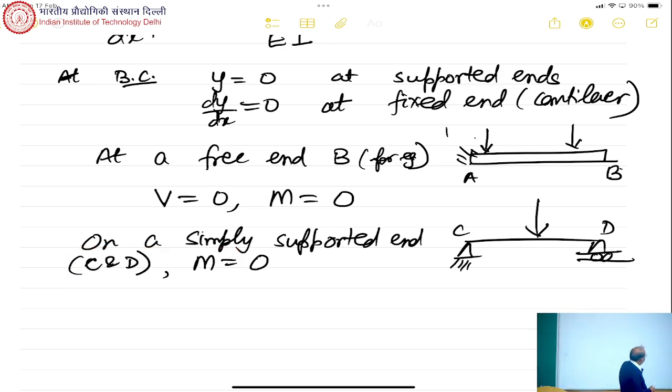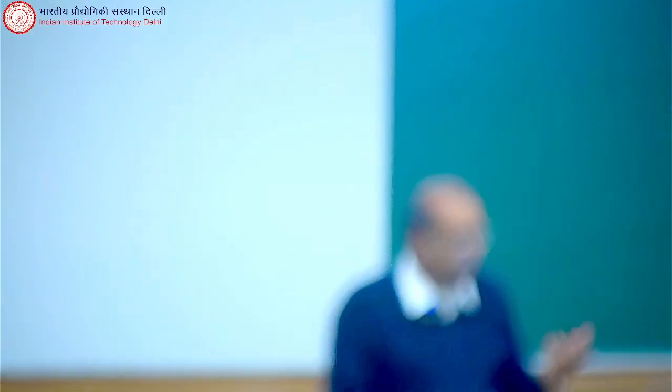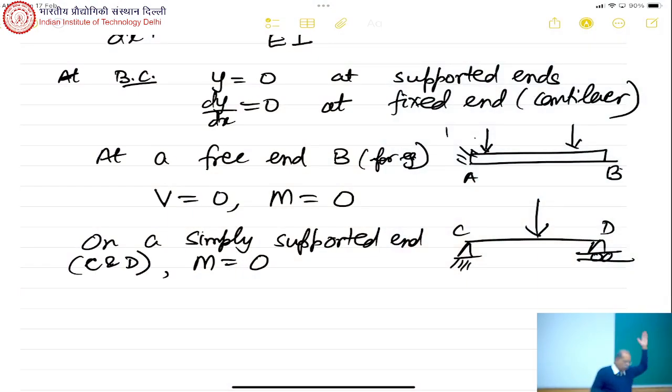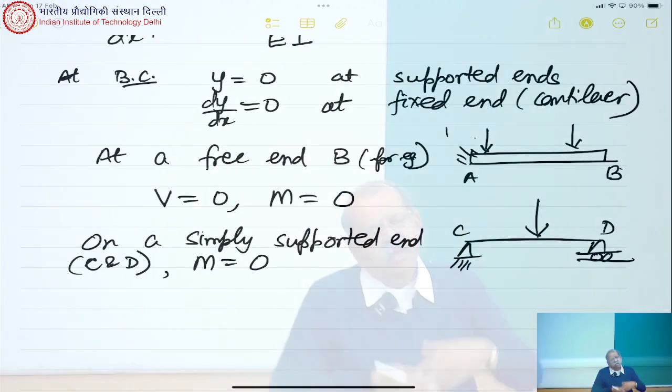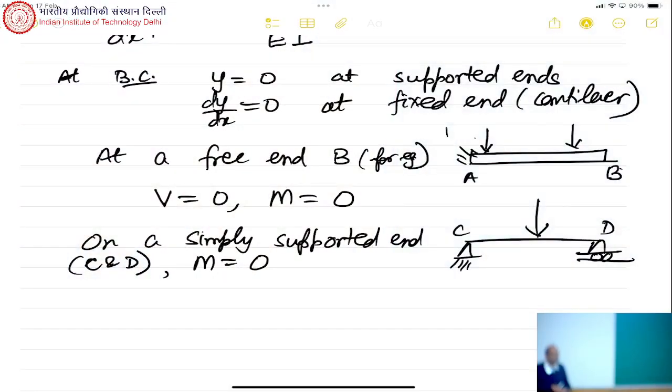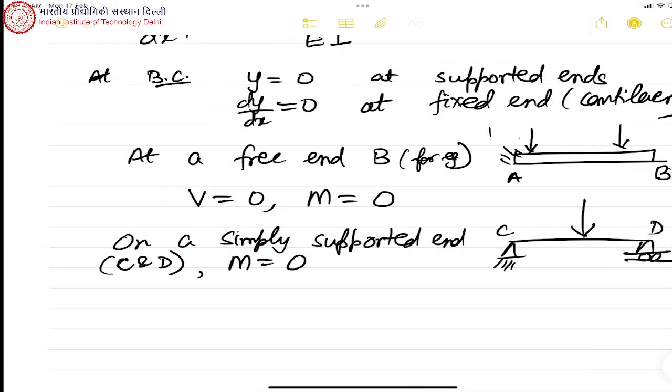So now let's look at an example. And one of the reasons why we are doing this is, first we will see statically determinate problems. In statically determinate problems, you'll realize all we have to do is integrate the bending moment diagram and get our answers. But what I will come to in this lecture is that this becomes a very good method to solve statically indeterminate problems. And let's see how to do that.